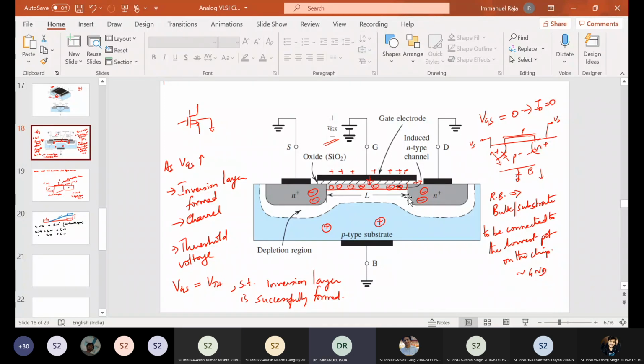And the US government also wanted to establish a big 5 nanometer foundry through TSMC in the US, and that was big news some months back, right? So I think as of now, what people are headed towards is 5 nanometer, although I don't think it's very widely commercialized. Most of the latest commercially available ICs might be in the 7 nanometer or 10 nanometer technology nodes, or many of them might be in the 16 nanometer, 14 nanometer FinFET technology node. Whether they can go below 5 nanometer, that's what all the industries are breaking their heads over.